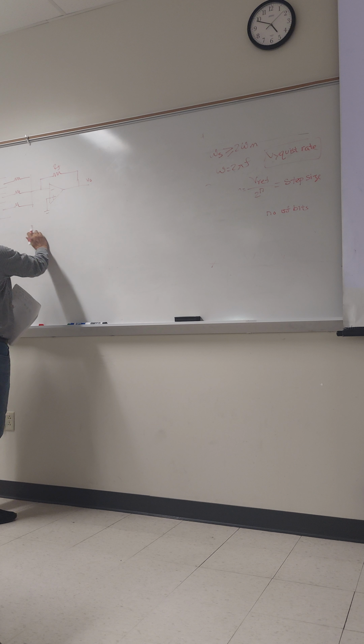You added 0.2, so on the receiving end you can subtract that 0.2 also. So this is in your hand. This technique is known as dithering. Okay, these are a few questions we found from our previous lecture. We also mentioned how we can do low pass filtering and what the quantization error is. I will upload this Word file.